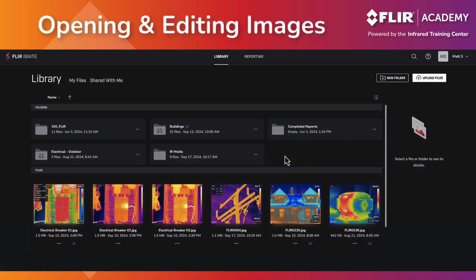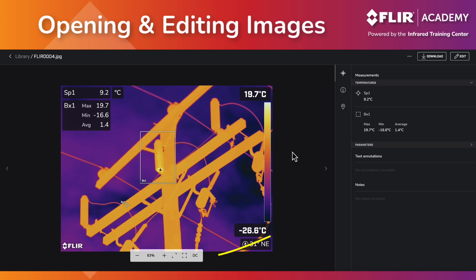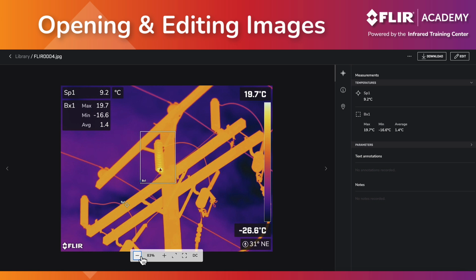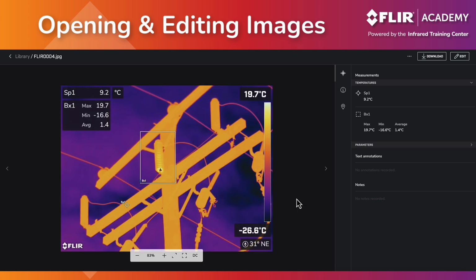To open an image in Ignite, double-click the thumbnail picture. This will open a full-size version, which provides the option to zoom in and out using the plus and minus buttons located on the toolbar. The digital camera or visible light photo can also be viewed by selecting DC. Click IR to return to the thermal image. The measurement or parameter data from the image is displayed here on the right. This includes spot temperatures or area box measurements, plus all the parameter information, including location, repair recommendations, equipment type, and more that were already saved in the camera.